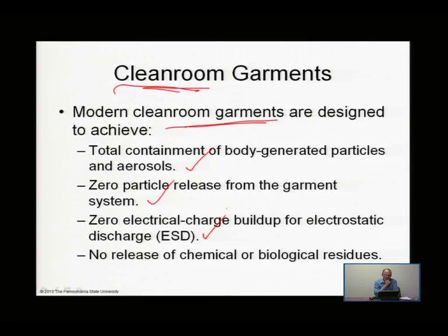And so you have to make sure that there's not this situation where electrostatic charge can be built up by the human walking around, the human touches something, it discharges, and that inadvertently affects the product you're trying to make. It all gets down to this issue that the whole processing sequence, whatever you're doing, has to be completely under control. There can't be something happening like an occasional electrostatic discharge.